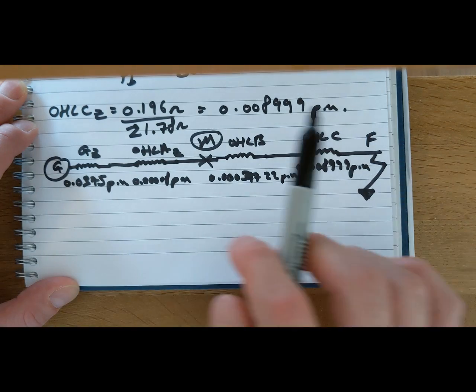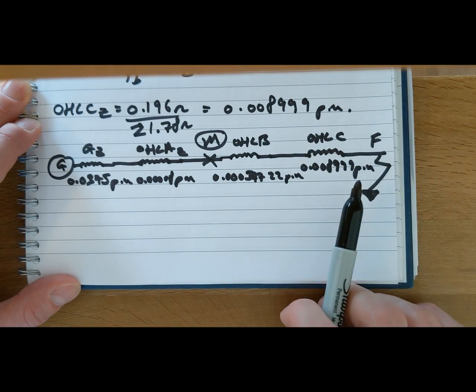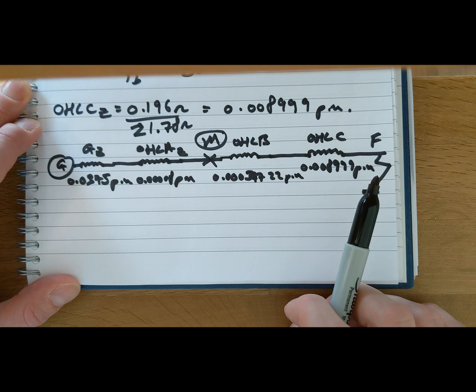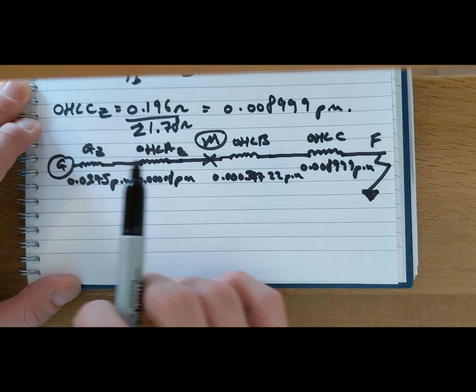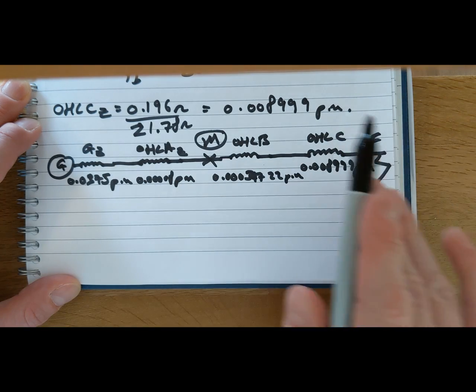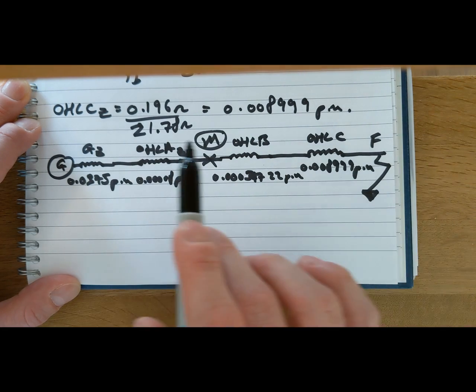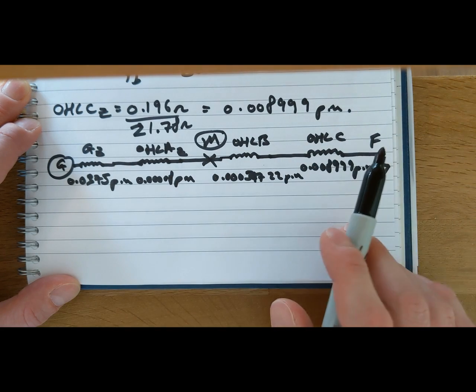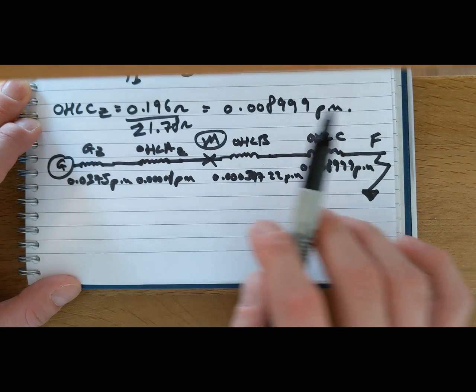And this is what makes per unit so useful in power systems engineering. If we take account of the turns ratio of the transformers in the bases, then we can neglect them from that point. And there's obviously hundreds and hundreds of transformers typically in a transmission network or a distribution network, and therefore all this reflecting through the transformers by the square of the turns ratio or the turns ratio can then be neglected, making calculations so much simpler.